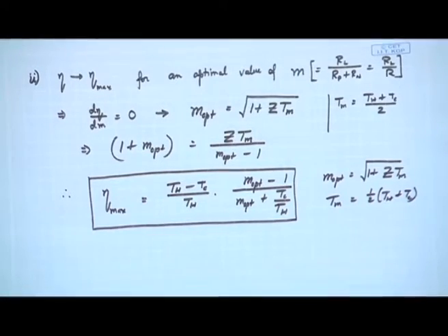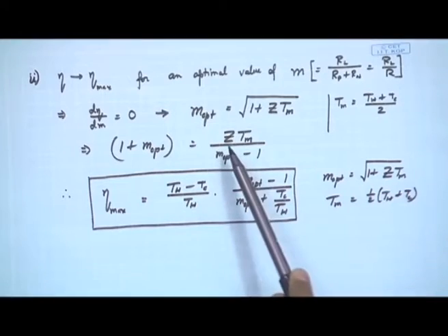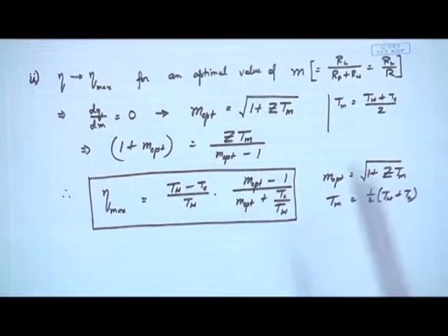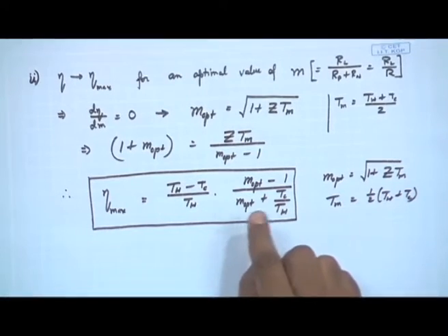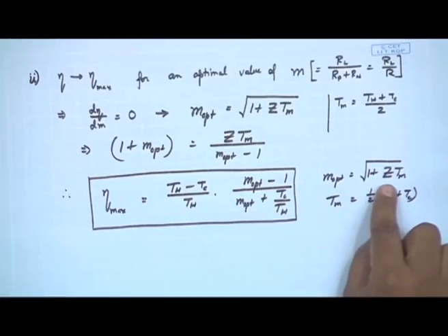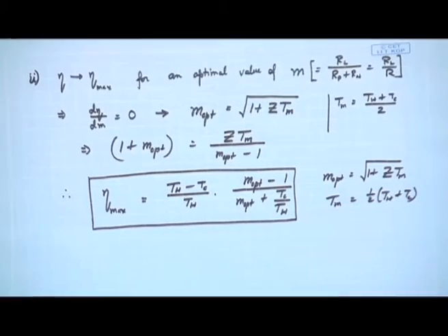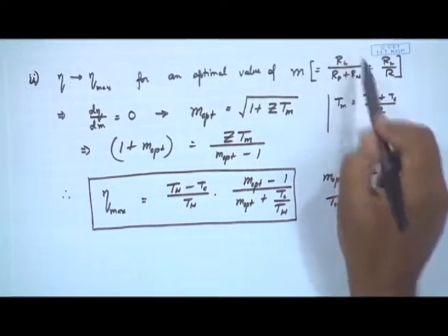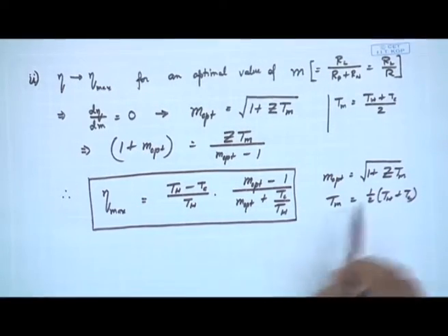We will first play around with the geometry of the thermoelectric elements such that this z is optimized and we get that z max value, and then in order to play around with m and satisfy this relation, we will alter the external resistance value RL. Okay. So, we will only play around with RL, and that is how we are going to get this value of m optimum. Okay. So, it is possible.